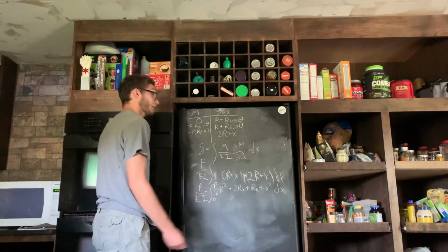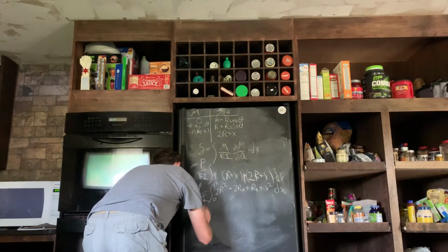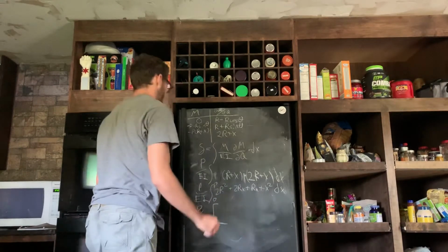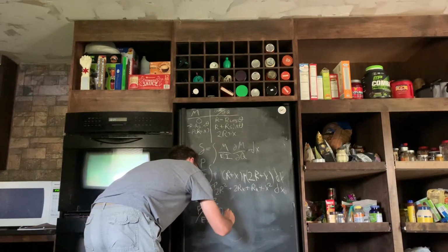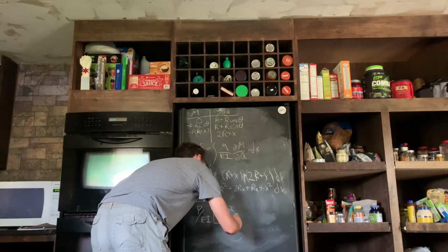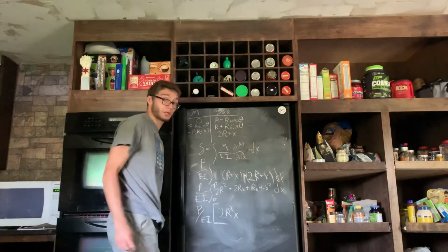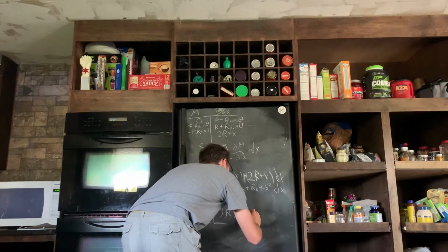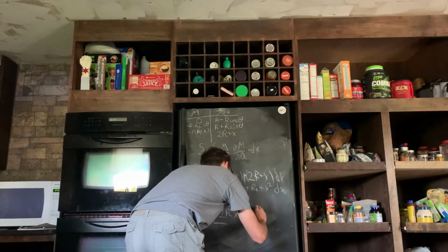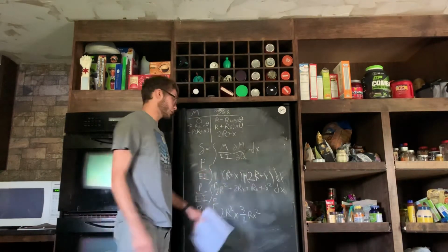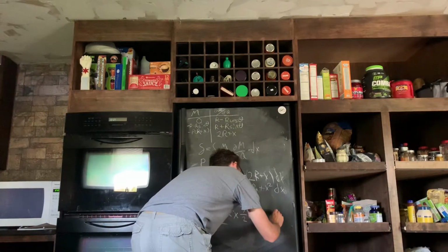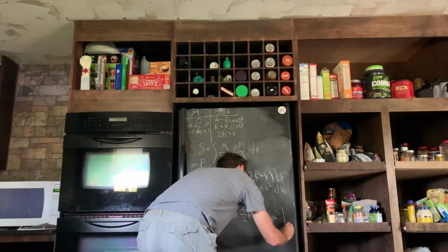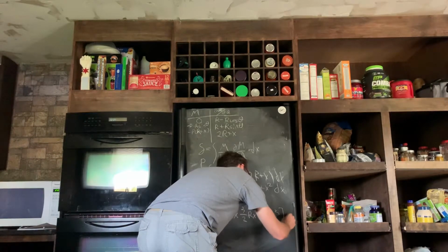So we end up getting P over EI, this is my integration area, 2r squared x, these two can be combined to become 3rx, so it'd be 3 over 2 rx squared, and then x squared would just become 1 over 3 x cubed, and then we need to plug in from 0 to L.